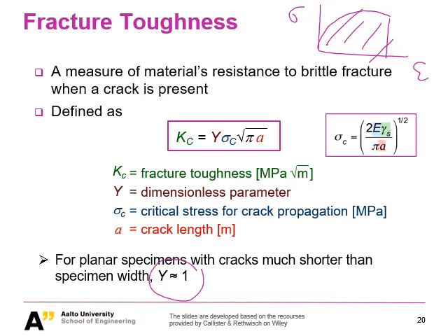If I just bring the critical stress definition here, you can probably see the reason. As I said, the sigma C is an intrinsic value, but it is reflecting both the material intrinsic property and also the crack. And we want to have a value that is completely on the material side. We don't want to know how big the crack is, whether it is small or large.